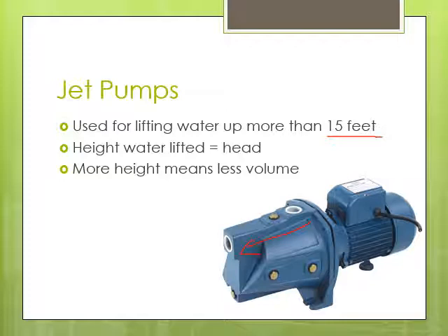An important thing to remember about ponds, so let's say here's your pond, right? It's full of water. There we go. Full of water in the beginning of the summer. As the summer goes on, the pond gets lower, which means your suction height becomes deeper, right? So you should, again, plan for all scenarios when selecting pumps.